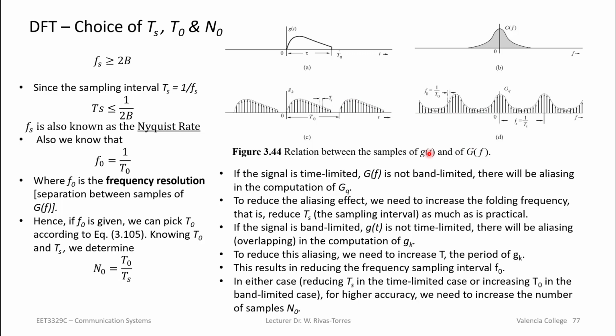We put it through a filter, and a filter will have a finite bandwidth that we can talk about. Let's say it's the 3 dB bandwidth, which is half the power, and not the 95% that we were talking about. It's 50% in this case. But let's say that that's what's important to us. It could be bigger, it could be smaller. It all depends on what you're doing.